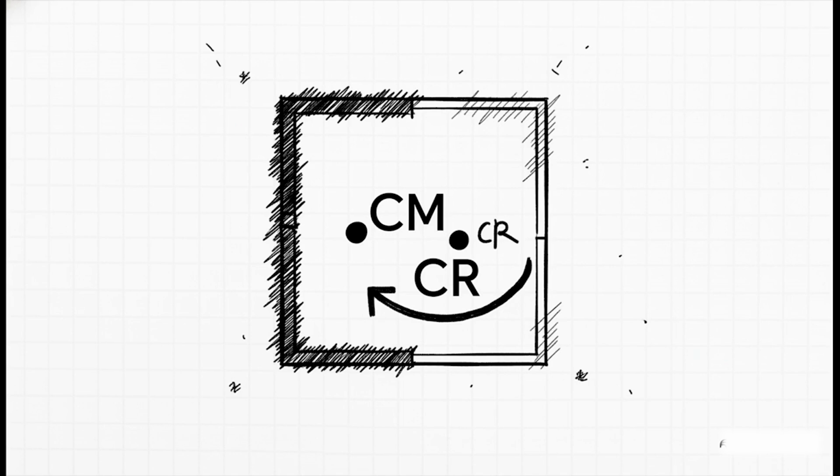Next up is stiffness asymmetry, and this one is probably one of the most common and hazardous out there. Just imagine a typical corner building in a city. You might have solid brick walls on 2 sides, but the other 2 sides facing the streets are all open with glass storefronts, right? Those super stiff walls pull the center of rigidity way over towards them, creating a huge gap from the center of mass. It's basically a built-in pivot point, just waiting for an earthquake to make it rotate.